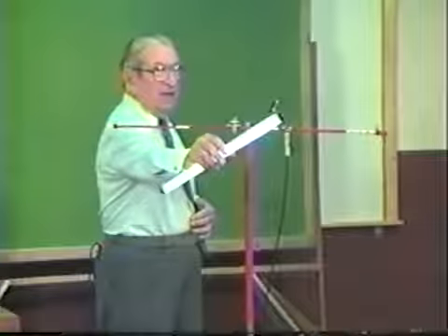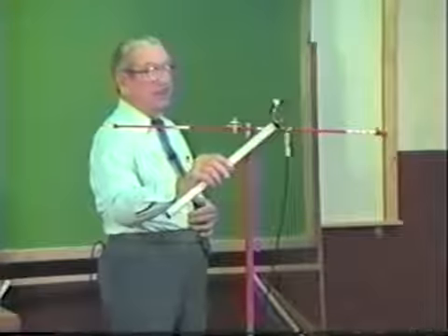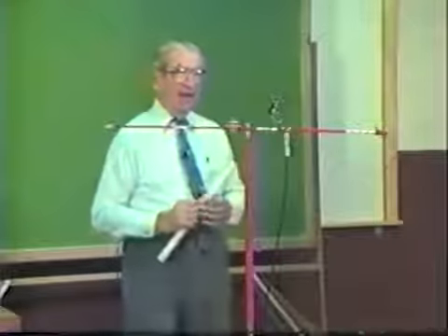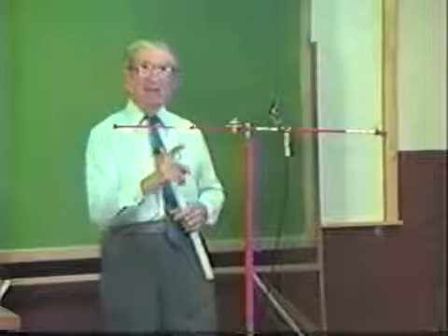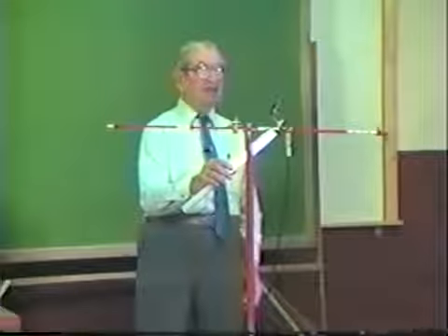If I put the same lamp toward the center of the antenna, it's not lit at all. Don't forget, this is one bar of aluminum. The other end of the antenna has a voltage loop. By the same token, if we bring this toward the center, you don't have the voltage loop, you have the current loop. So you have to be able to understand what they mean by standing waves, and this is a very, very vivid and visual demonstration of the standing waves of voltage and standing waves of current on this dipole antenna.